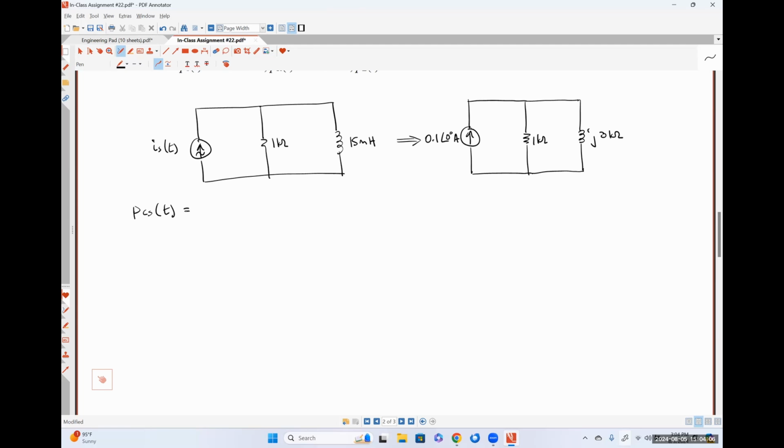because it's a source, so it's not a resistor, capacitor, or inductor, we have to use our generic equation. So that's 1/2 Vm Im cosine(theta v minus theta I) plus 1/2 Vm Im cosine(twice omega t plus theta v plus theta I) relationship.